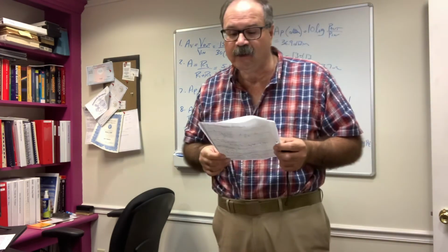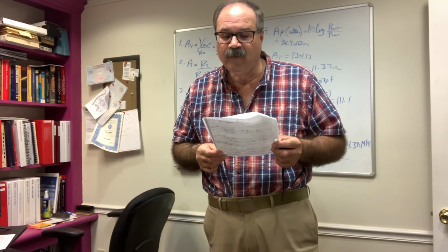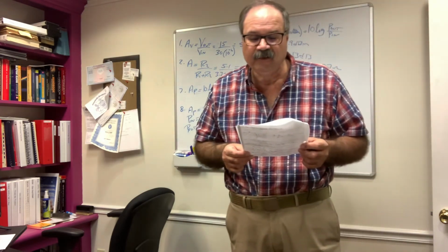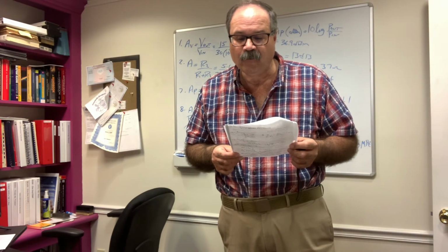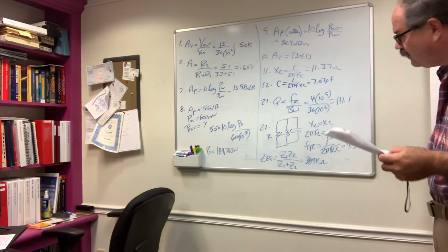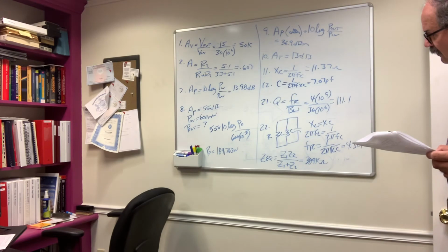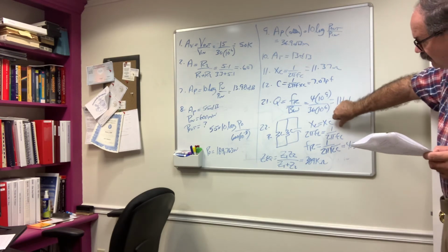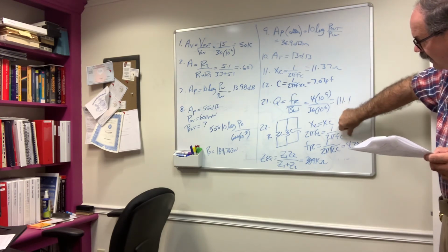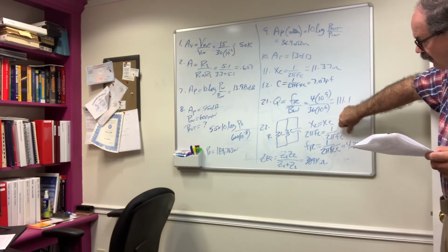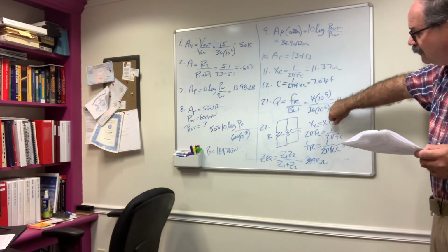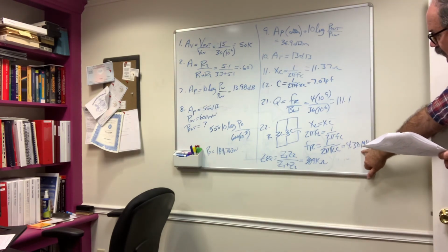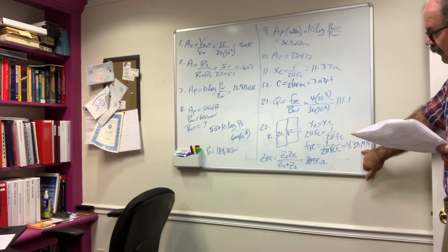And the last question, question 22. Find the impedance of a parallel resonant circuit with values listed. The inductor is 60 microhenries, the resistor is 7 ohms, and the capacitor is 22 picofarad. So we have our parallel RLC circuit. Remember, at resonance, the inductive reactance is equal to the capacitive reactance. So I algebraically solve for this expression. Ultimately, I'm looking for resonant frequency, where resonant frequency is equal to 1 divided by 2 pi multiplied by the square root of LC. Plug these numbers in. I'm going to get a resonant frequency of 4.38 megahertz.